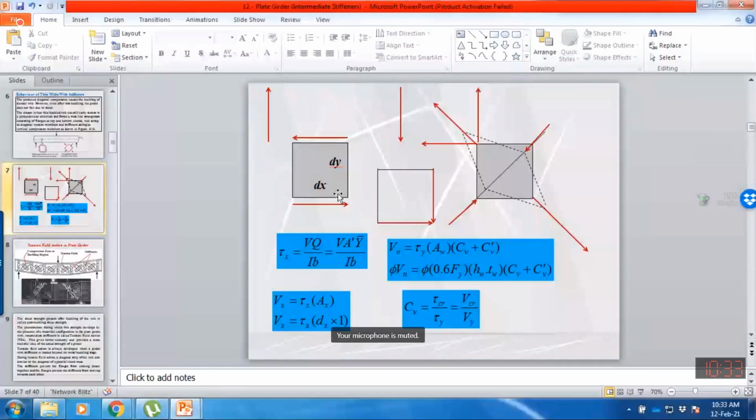And this force tends to produce a moment in the counterclockwise direction. So it means that rotational equilibrium is not equal to zero, or not balanced. These two forces are perfectly equal in magnitude and act in opposite directions, so these are called a couple.